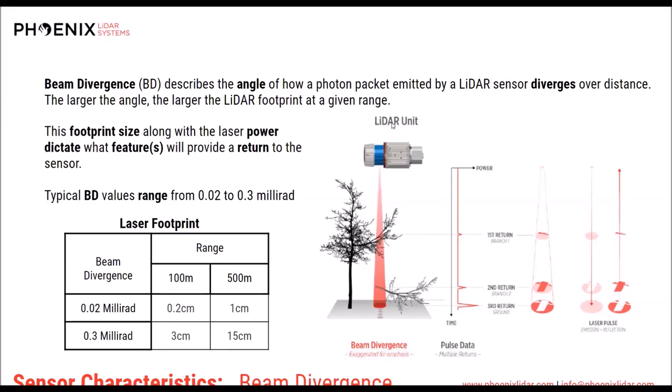Thank you. Okay, well, let's do one more question. For forestry application, how would you compare the Mini Ranger 2 versus the Scout Ultra? Given that the Mini Ranger 2 can have multiple returns and has a smaller beam divergence than the Ultra, whereas the Ultra has a long range and a 32 laser array. I would say they have very different use cases for a forestry application.